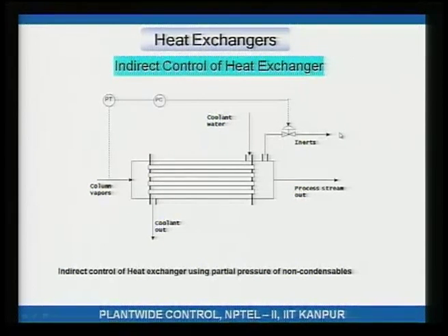Okay. So, you are putting in the coolant, and let us say the cooling valve is fully open. How do you control the pressure of the column? You see, that is by adjusting the inerts or the non-condensables that accumulate. You open this valve or you close this valve. How does this work? Well, that is about it. I do not think there is much to be explained here.